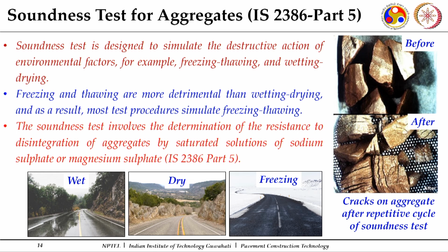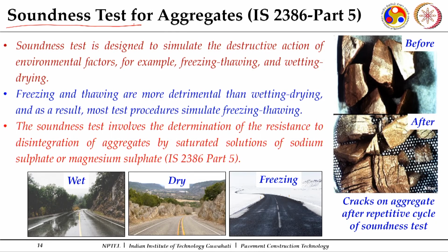Now, another important aspect which is usually carried out to judge the durability of the aggregates, or their resistance towards different environmental factors, is soundness. This is especially done when the aggregates have higher water absorption. Certain aggregates, sandstones or laterite rocks, have a tendency to have higher water absorption, and they may disintegrate or break under change in the environmental conditions. That is usually evaluated in terms of the soundness test for aggregates carried out as per IS 2386 part 5.